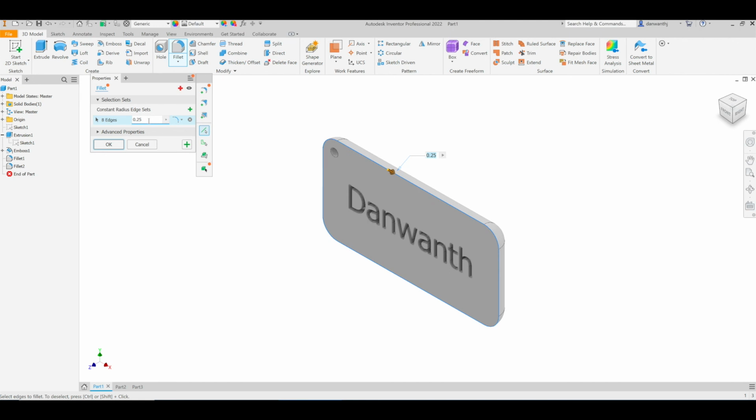So it might be interfering with the other fillets, it might be interfering with the hole we created, things like that. So if it interferes with anything, Autodesk Inventor will not carry the fillet. We're going to go with 0.05. The reason is this is the fillet that works and it doesn't interfere with anything else.